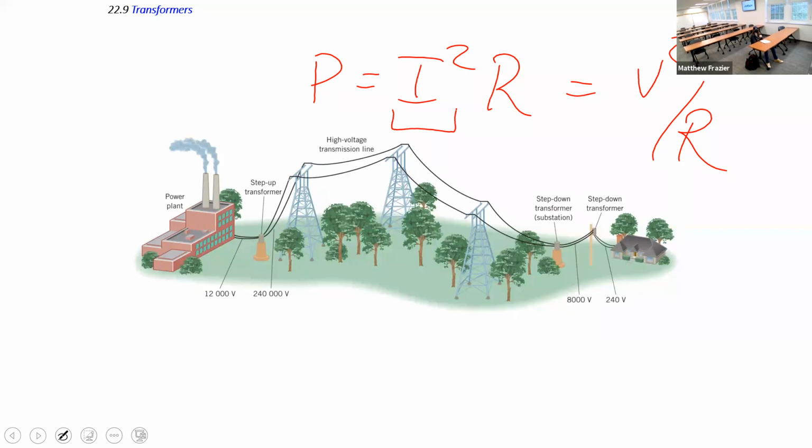Well, the truth of it is, it's not just the voltage and the power. You can also fiddle with the resistance, right? So if you have a high current, to minimize the power and you can't change the current, you have to make big fat wires to have low resistance, right? So for a given level of loss that you're acceptable with, if you increase the voltage, you can get away with larger resistances. In fact, larger resistances end up with lower losses, oddly, because current's not flowing as hard.